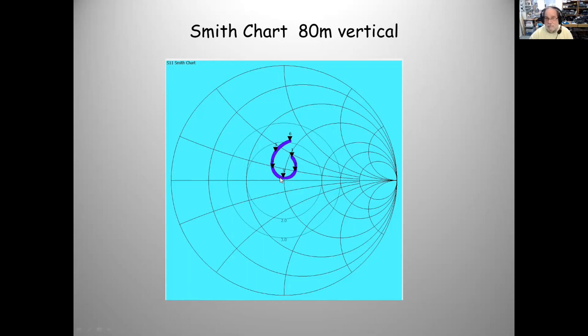Well, at night. Smith chart. Because it's curlicuing up here, is that better than down here? No. The distance to the bullseye determines the SWR, not if I'm left or right or above or below, and I'll show you that in a minute.